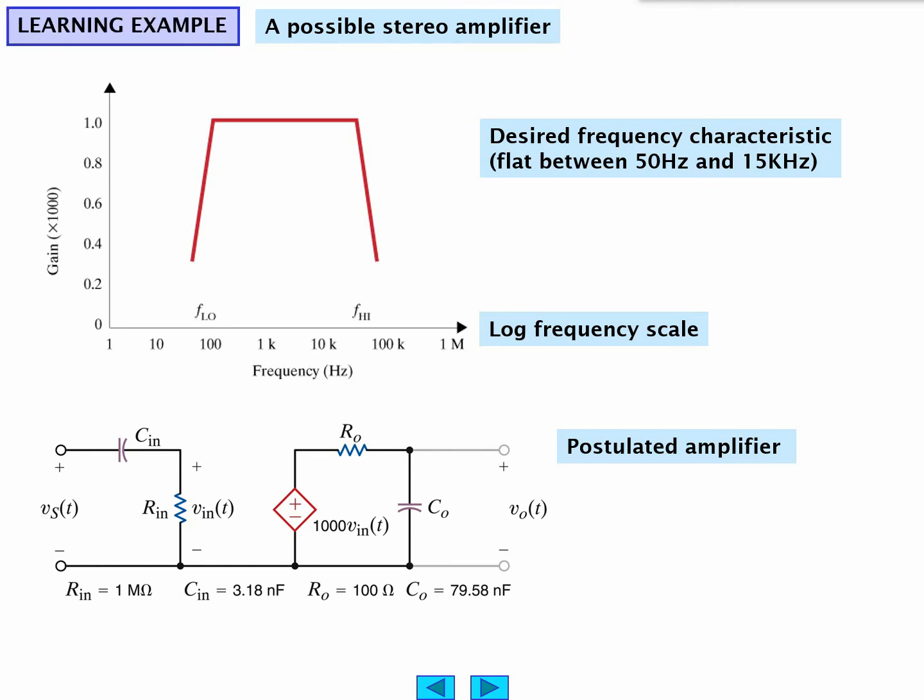Okay, I'm back, and we're going to look at a filter network that's intended to have a roll-off, so that you have a flat gain over a certain frequency range, approximately 100 hertz to 100,000 hertz, and that it's not supposed to pass anything below approximately 100 or above approximately 100,000. Or here we go, flat between 50 and 15 kilohertz. Okay, so we come over here and we're given some facts